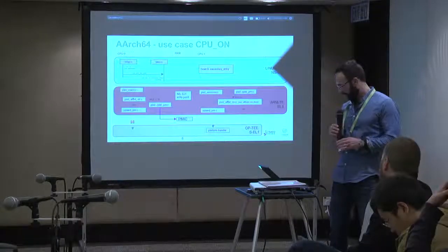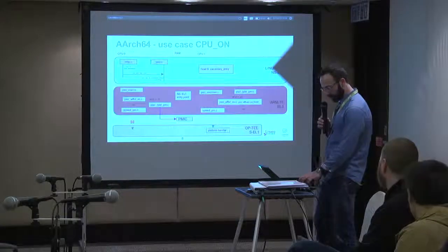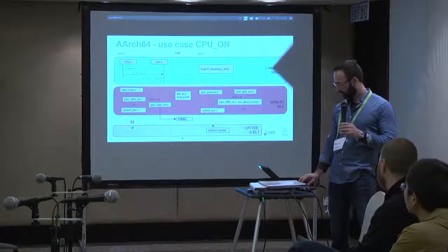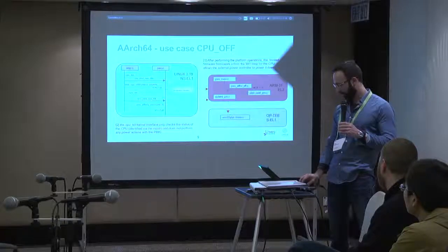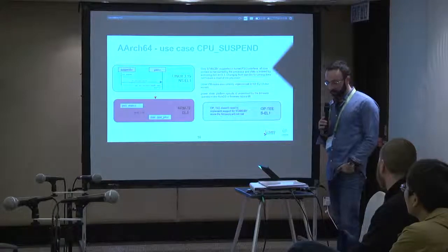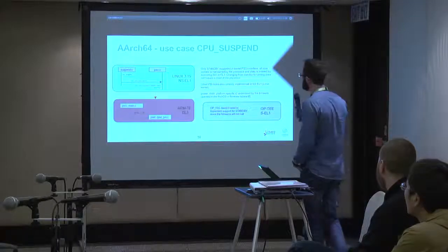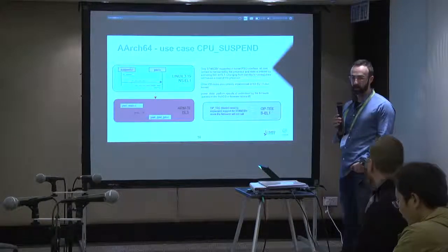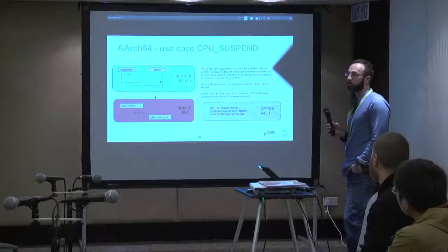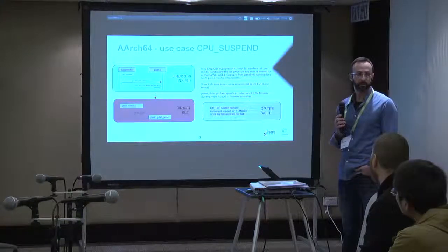So, have you gone through this already, CPU on and off? Yep. So I think CPU on, we've covered this one, haven't we? Yes. CPU off, I think we've covered this one as well. Suspend, that's interesting. The interface that PSCI presents supports standby and power down operations, and together with the operations, it creates a couple of fields where you can customize your plan.